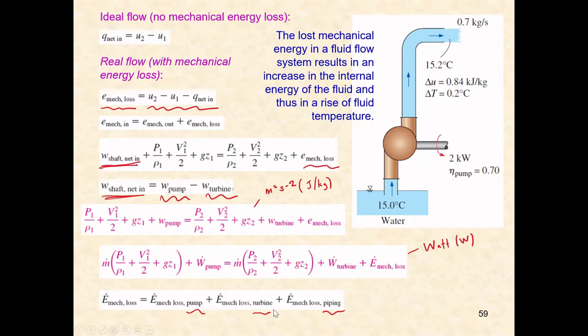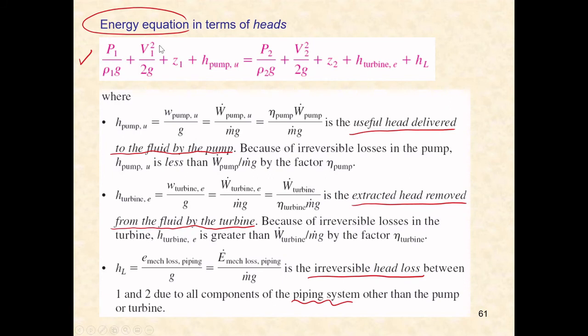throughout the whole derivation process, you will come to the realization that you have the Bernoulli equation that you can compare at two different points, point 1 and point 2. You have H pump located on the left side of the equation, and H turbine located on the right side of the equation, as well as HL. HL is the head loss. Head loss accounts for the major loss as well as the minor loss. This loss is because of the piping system.